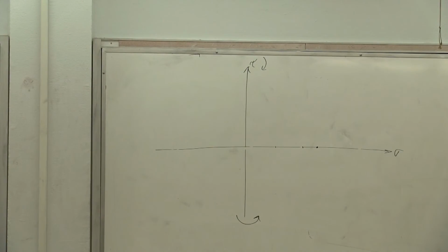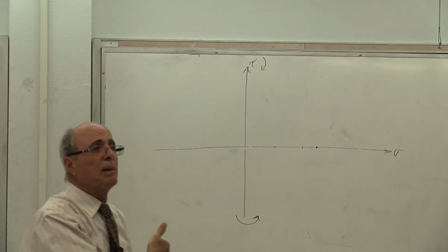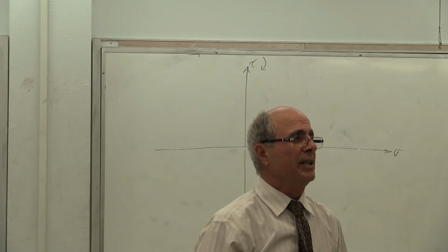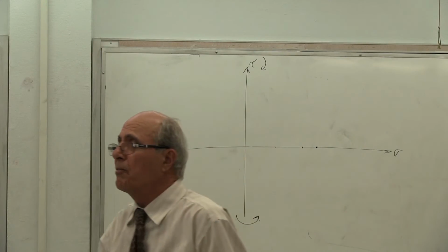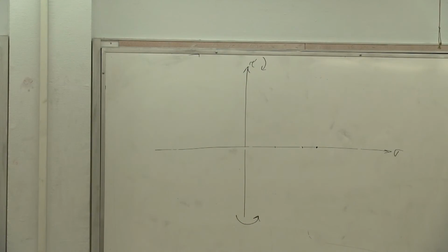The shear for us is negative, and look at it, minus here, it is minus 4.7. That's the way we express that. But for Mohr circle, one of them is positive, one of them is negative. Now there are different books, different scenarios. I don't know how your instructor does, but it doesn't make any difference. You can put the positive on top, negative on the bottom, or the other way around.